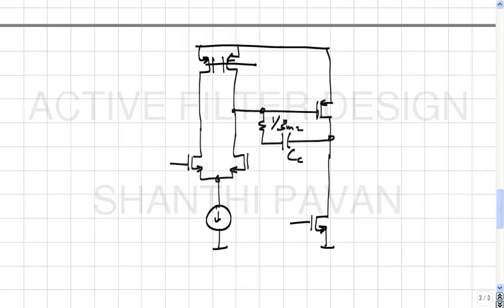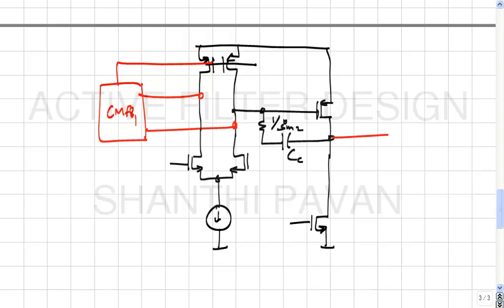All right, and we were talking about how, at least one straightforward way of implementing this is to have a common mode feedback loop which goes and tweaks the output common mode voltage of the first stage to be some known quantity, and similarly you have CMFB2 which goes and tweaks this current source as well as the other symmetric current source corresponding to the other side to keep the output common mode voltage the same.